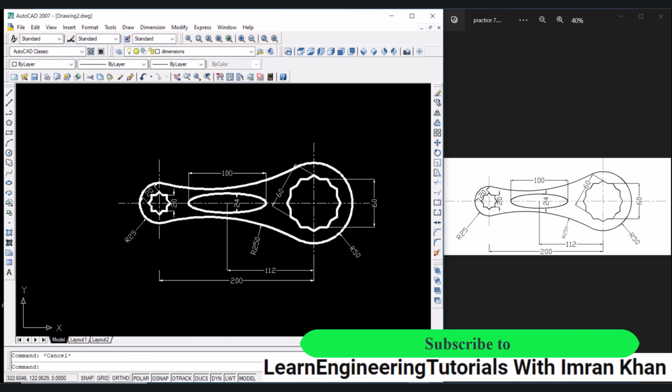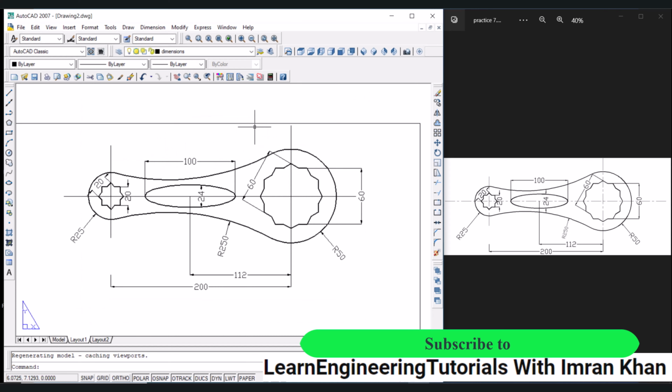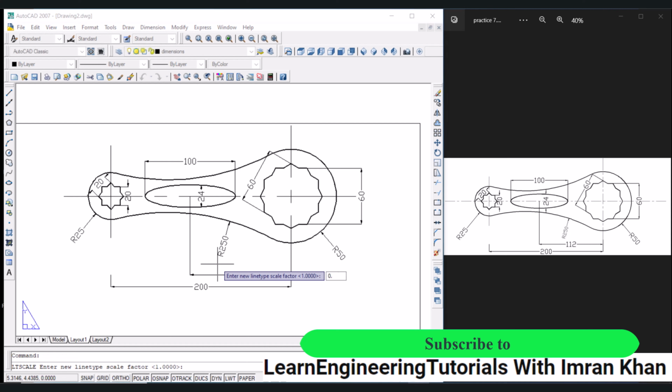Now if everything looks okay, let's view this object in the printed form. So for that we have to click on layout. Now in this view we can see that the line type of the center lines is not correct, and that means we have to utilize the LTS command, LTS enter. Let's reduce the scale to 1 enter. Press enter again, let it be 0.2 enter, and now you can see them clearly in the printout.